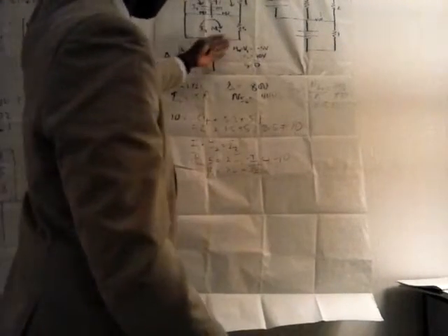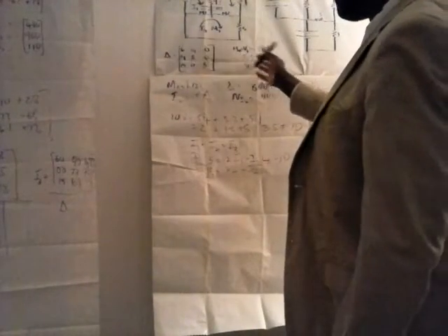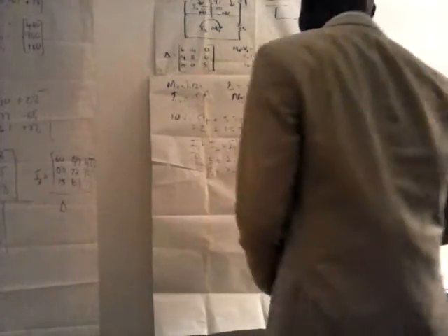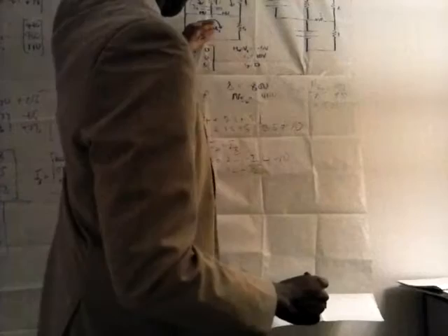The principle of the determinant was also correct, but like I said, there was some mistake made with the signs or in the calculation of the determinant, which is not infrequent. And because we're dealing with determinants greater than 2 by 2, we're dealing with 3 by 3s and 4 by 4s, mistakes can be made. So I'm going to leave it at that and ask you now to recheck it by using KVL and KCL around this loop. If you have 3 unknowns, we could bring in the 3rd mesh and solve it, independent of the determinant method.